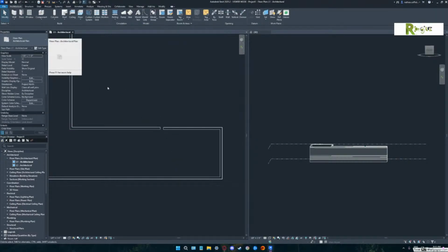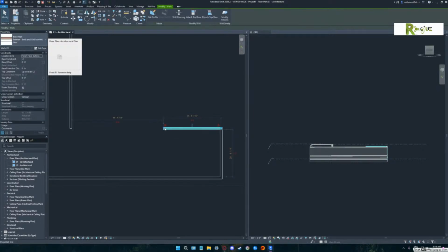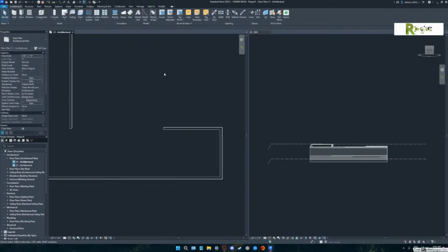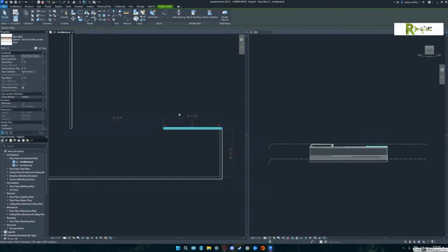All right. So I'm going to show you first what I would have had to teach most CAD people to do. They would delete one of those walls, right? Go ahead and delete one and hit delete. Now pick on that other wall. And when we pick on an object, watch across the top of the screen. Automatically our modify toolbars come in. If you pick back in white space, you'll notice that'll go away and you'll be back on the architectural tab drawing walls. So what most CAD people would do is pick that wall.